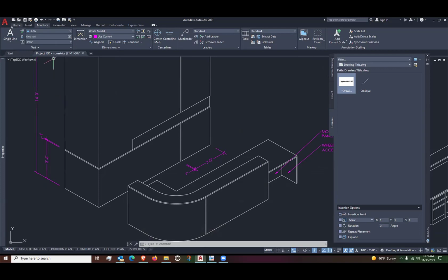And I'm going to add some text. So I'm still on my annotate here, and I'm going to go to single line text here. I'm going to pick a start point, and I'm just picking a point here, and it's asking for the rotation angle, and it's saying 330 degrees. Let me put my ortho on. So I want to tell it I'm going to go this way, from left to right. And now I've got the cursor and I can put some text. So, I don't know what, ABC company.